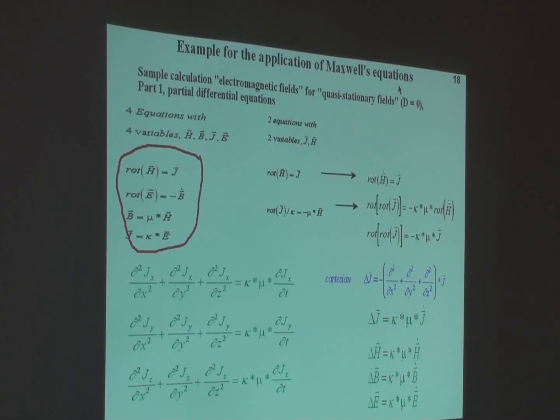They say, if you have an electrode arm of 400 or 600 millimeters, and you have only 1 centimeter, the current only goes there, and then it's easier to calculate. This 1 centimeter does not matter in the reactance afterwards.